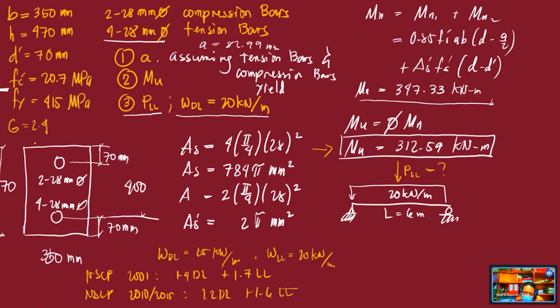So to solve for gamma, the unit weight of concrete, this is equal to specific gravity multiplied by the gamma of water. For concrete, this is 2.4 multiplied by 9.81. If gamma of concrete is given, what will you do with it?